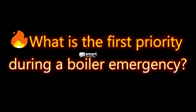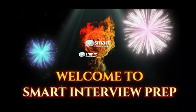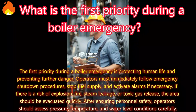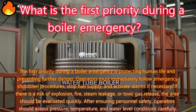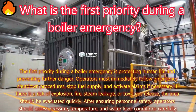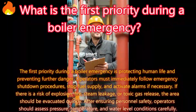What is the first priority during a boiler emergency? Answer. The first priority during a boiler emergency is protecting human life and preventing further danger. Operators must immediately follow emergency shutdown, stop fuel supply, and activate alarms if necessary. If there is a risk of explosion, fire, steam leakage, or toxic gas release, the area should be evacuated quickly.